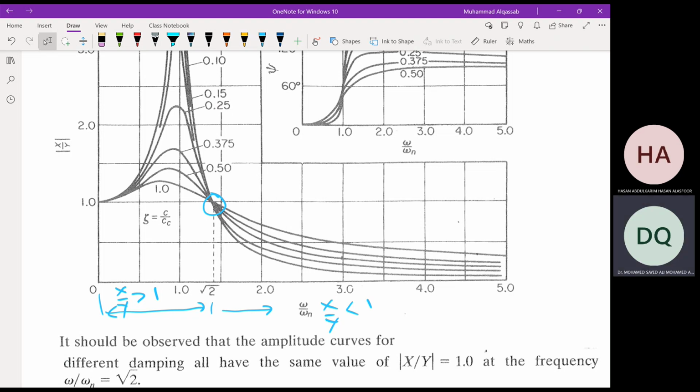It might be bigger than 1 because this is a vibrating system. Once you put in the spring and the damper, you are putting elastic members in between, and you could expect that the vibration can be higher than the base. Okay, so the frequency ratio should be greater than square root of 2, and this will be based on k and m as well as on c.